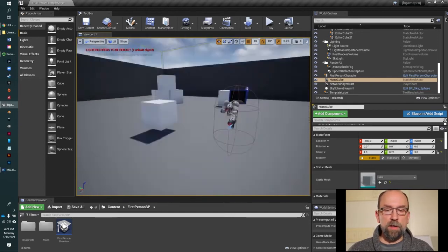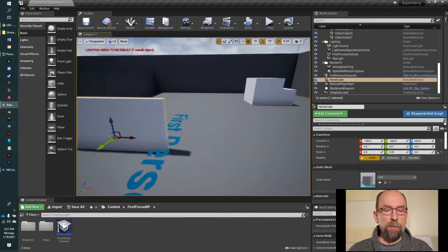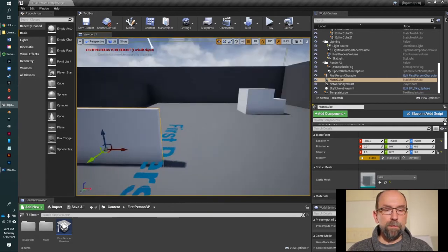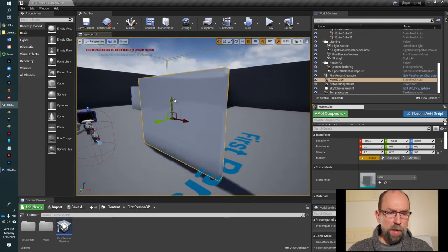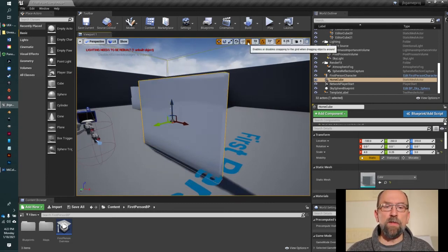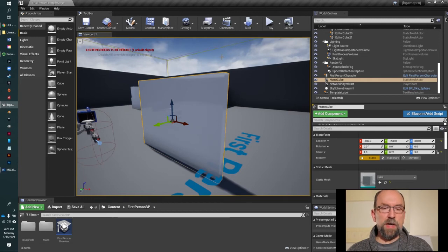All right, a couple other things about manipulating them. We'll talk about snapping here in a moment. So let's talk about snapping. So right now I am snapping because I have this snapping to the grid, because I have the grid snapping activated right here. Now if you don't see these, you can simply hit Control-Shift-T, and that's a toggle, that turns on and off these controllers. If you're on a Mac, it's probably Command-Shift-T or Option-Shift-T.